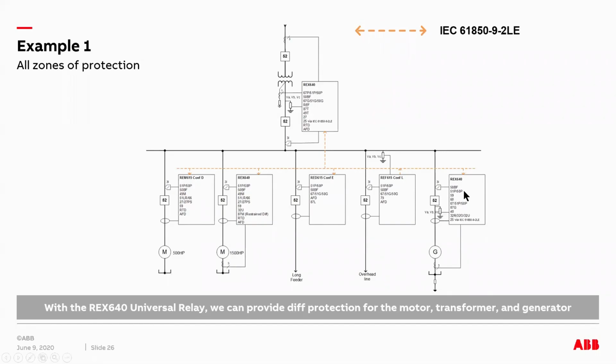So with this, all the standard protection can be achieved, the differential protection can be achieved, and in addition, we now have the ability to share the voltage between the devices. Which means the bus voltage can be shared between all the devices, and if there is a line voltage to be checked for synchronizing purposes, that can be checked as well. For example, here in the generator protection, you have a line PT or line voltage sensor, and then the bus voltage sensor coming from the sample values, and it checks the synchronizing condition before you can close this breaker and bring the generator onto the bus.